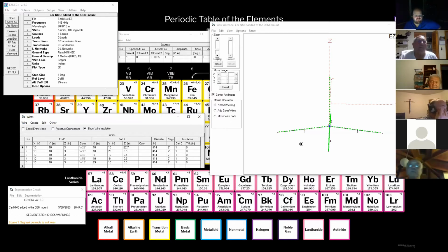So let me give you some recommended settings here. You're going to have wires. By a matter of habit, I run odd numbers and quite often prime numbers in here. Does that matter? No. But I try to make sure that I have no less than 1 segment per inch in my antenna.